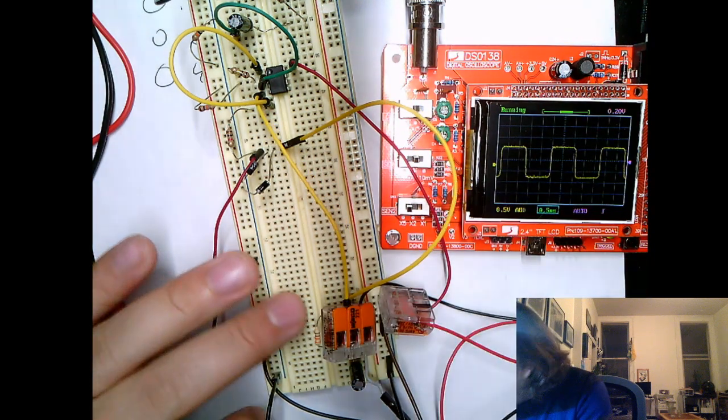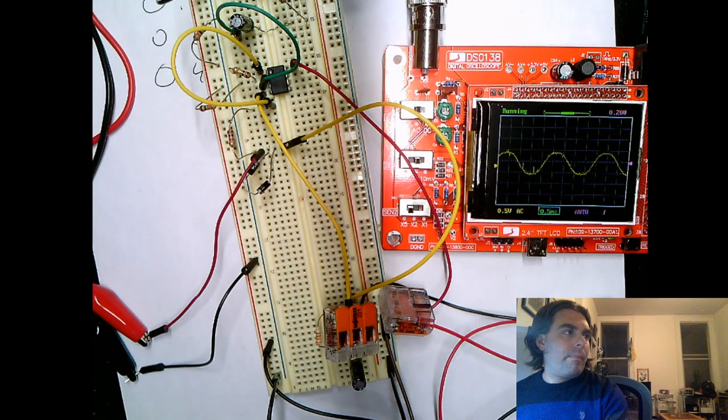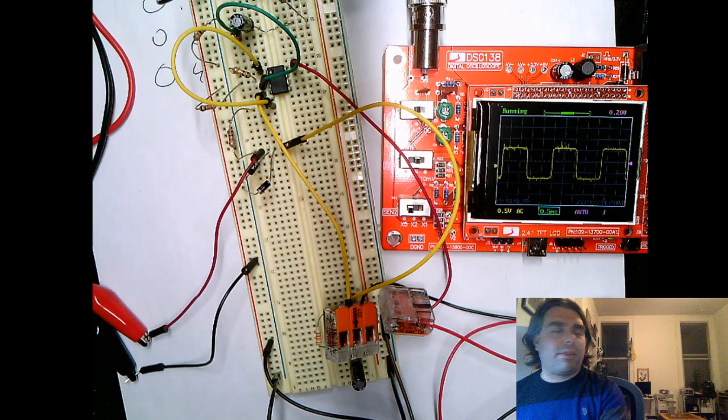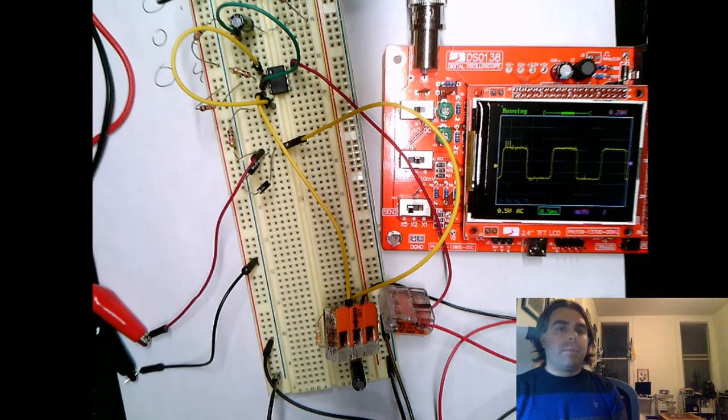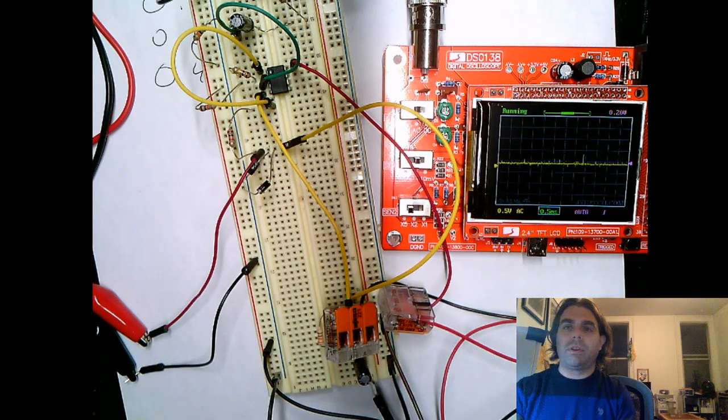We don't need to listen to that. Let's unplug that. So, check out my oscilloscope. There's my wave, right? As I increase it, I'm chopping now both the positive and the negative sides of the wave. So I get almost like a square wave, right, as I increase the volume. I'm clipping both sides. This is as loud as I can get. And I've pretty much turned this sine wave into a square wave. Let me stop this, and we'll put pulp back on, and we'll see how this sounds with actual music.